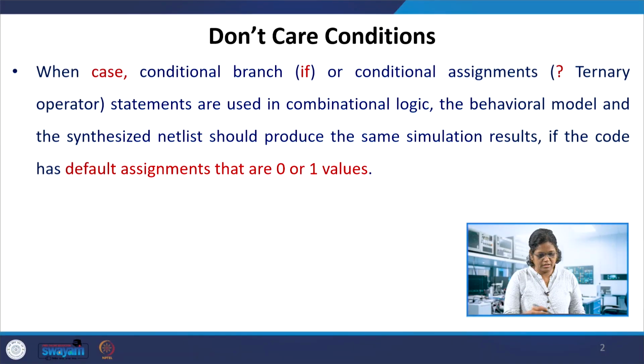If there is a case statement, an if statement, or conditional assignments like the ternary operator, they use combinational logic. In the synthesis process, using these three would yield similar results, that is, the simulation results will be the same if you write the same thing with case, if, and a ternary operator.